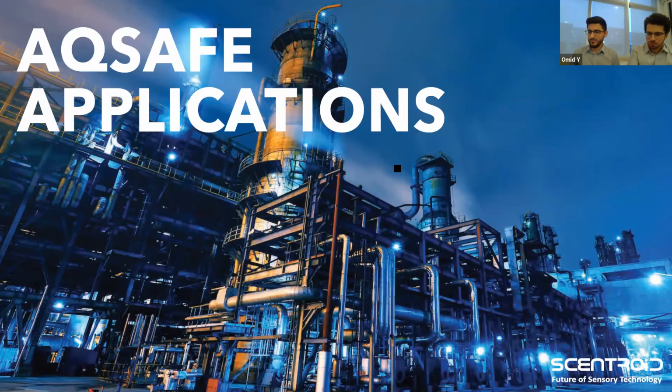If, for example, you're in an environment where you have large levels of ammonia, then we recommend having one unit on the top and one on the floor, because as you may know, ammonia, when it's dry, is lighter than air and it rises up, but when it's ammonia with water absorption, it becomes heavier than air and then it goes down. So if you're really interested in monitoring that precisely, we recommend having 2 units for that application. But again, it's on a case-by-case basis. So if you contact us, we can tell you exactly.